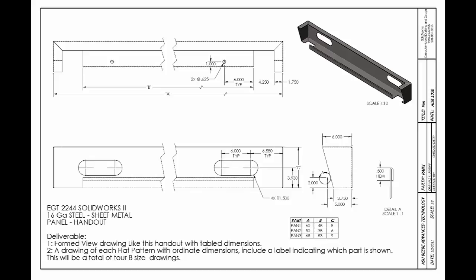I have a great deal of experience in sheet metal while working in the product engineering of a commercial refrigerator and freezer manufacturer. We always dimensioned our parts to the inside of the flange. We will keep this in mind as we design our sheet metal parts.